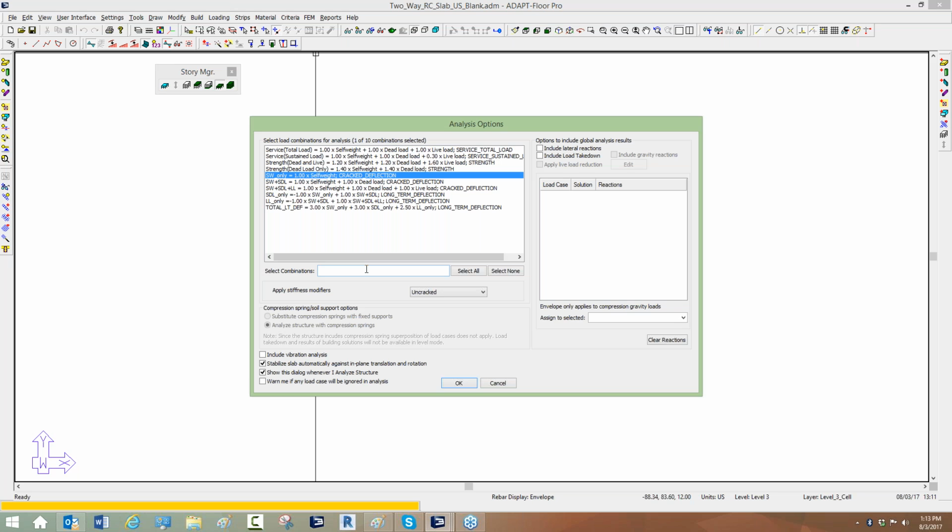And that's because your general frame analysis, if I run this, for example, using slab stiffness, this is what I'm referring to as the general frame analysis under some condition using this usage case, this could result in higher deflection because I've artificially cracked the slab by means of a stiffness modifier. And this could result in a higher deflection than the actual cracked condition, which is using the uncracked state as the basis for which the program determines whether or not the slab has cracked.